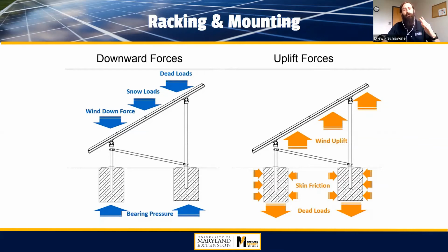And particularly if you have your panel tilted up really high, you're going to have a wind force that catches the bottom end of the module and could potentially, under severe conditions, pull or shift the unit around. Now, I've never seen a solar photovoltaic system lifted out of the ground, but I've seen similar things with greenhouses and high tunnels under high storm conditions. It'll pull the cement out of the ground because the foundation wasn't deep enough. And so that's some of the things you have to get into detail into.